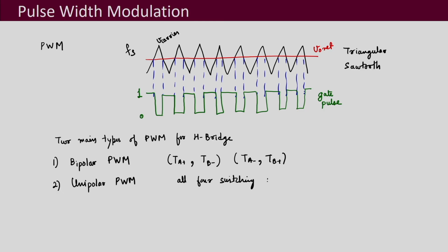And depending on the modulation method that we use, that affects the voltage waveforms and the current waveforms across different components, and then it affects the design process, because once your waveform gets modified, the voltage, current, and frequencies the component has to withstand change. Then accordingly your design also changes. So, that is why we will also be paying attention to the modulation method.